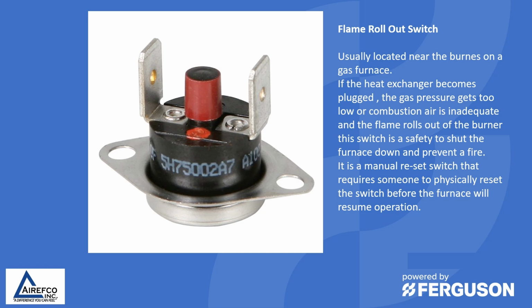If the heat exchanger becomes plugged or the gas pressure gets too low or combustion air is inadequate and the flame rolls out of the burner, this switch is a safety to shut the furnace down and prevent a fire. It is a manual reset switch that requires someone to physically reset the switch before the furnace will resume operation.